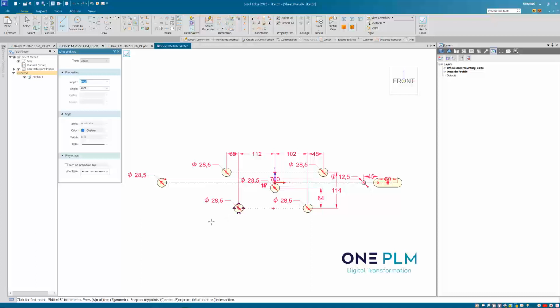So I'm going to start by drawing a line along the bottom, one up the side, and press the A key. That will allow me to go and create an arc. So I actually want two slightly different arcs. I want a slightly mellower arc here, and then as soon as you finish an arc, it goes back into line. So you can just press the A key again, and that will allow us to create a different type of arc. So now I want an even mellower arc, and then another arc, and this is going to be quite a sharp arc on here, which I want to try and take so it goes back to horizontal.